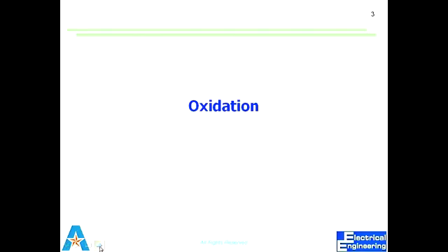So we looked at lithography. Let's look at oxidation. Most of the lithography steps that we do, we always have some hard layer first made up. Mostly that layer is oxide, and then we apply photoresist on top of that. Photoresist is what we use to transfer the pattern from the mask, and then we use that photoresist as a soft protection layer to transfer that design, that feature, into the hard layer beneath it, which is mostly oxide. How do we transfer that design into the lower layer?